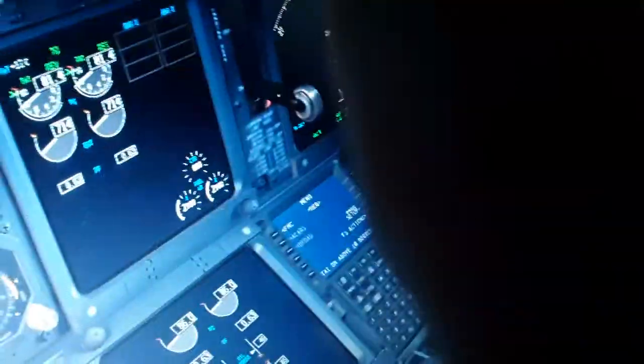So I'm gonna show you here. I told you the thrust levers. You can see the detent and the thrust levers now is in the idle. We have the flight detent. We have 50% here flight detent. We retract the reverse. Flight detent 50%. Maximum takeoff go around. So you can see.